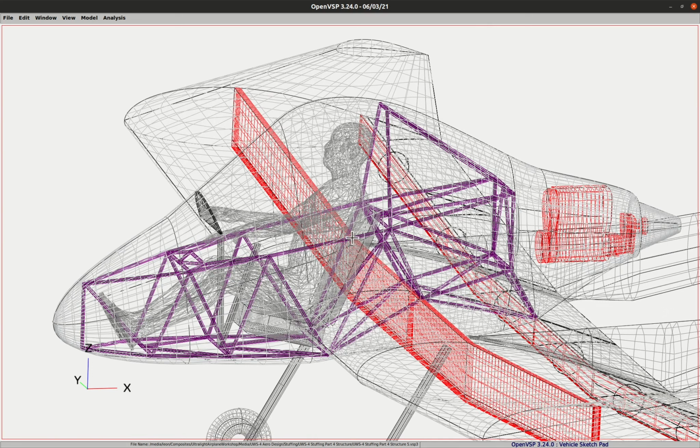In order to make this spar as light and as strong as I can, I want the carry through here to be straight. I don't want any cutouts. So our attach points will be right here at the top of the spar. And again, there's one attach point back here on this rear spar. I already talked about that.